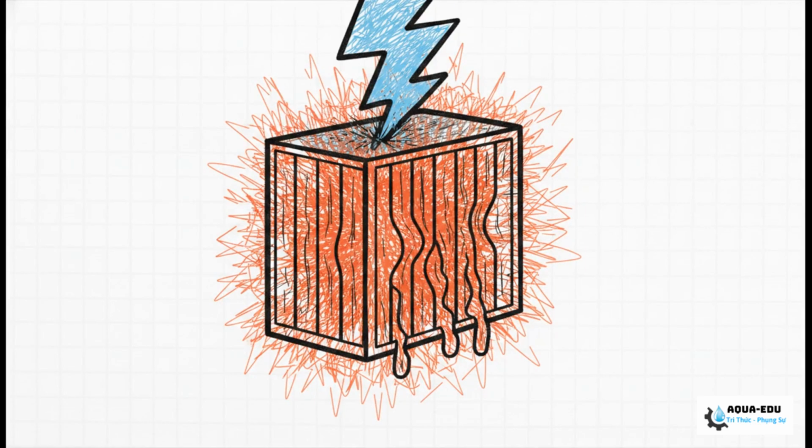I want to pause right here, because as someone who has seen millions of dollars of equipment ruined, I need you to hear this warning loud and clear. If you ignore these failing power symptoms, you won't just get incomplete deionization and bad water quality. That fluctuating current and high ripple causes intense localized heating. It gets so hot it will physically melt the internal partitions of the module. No joke, you will permanently destroy the equipment from the inside out, leading to catastrophic downtime and massive replacement costs.